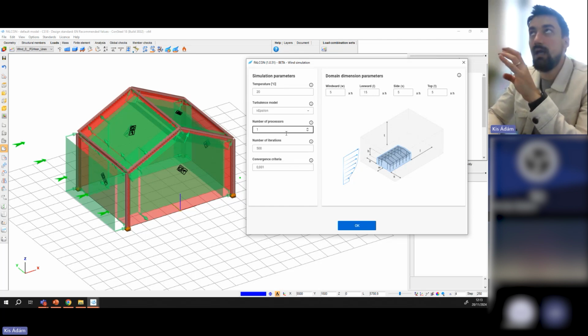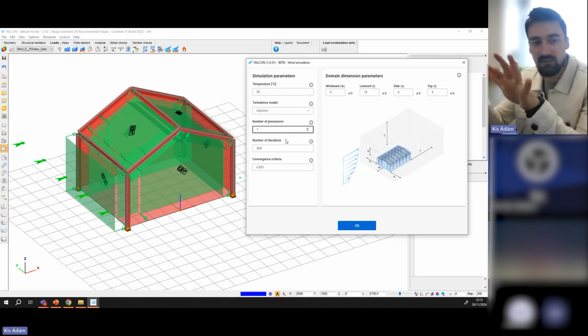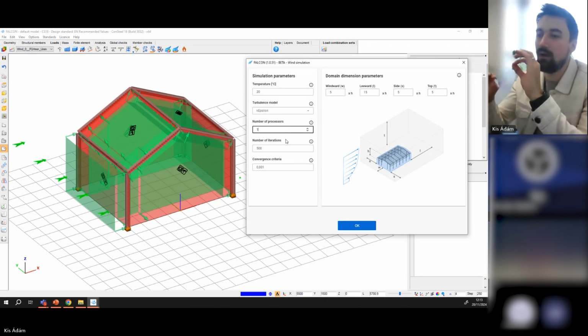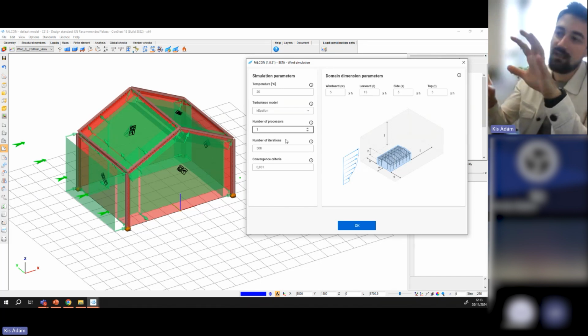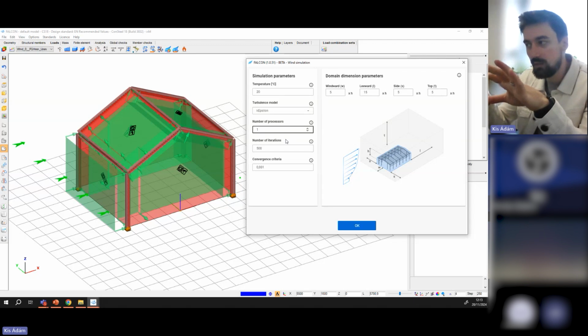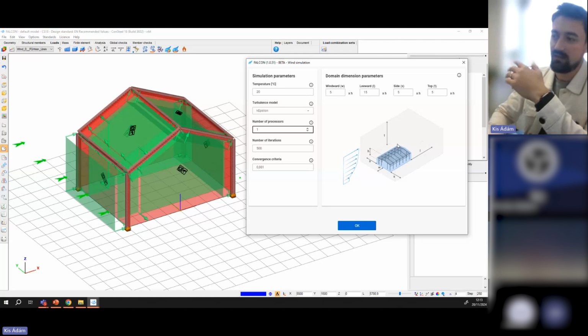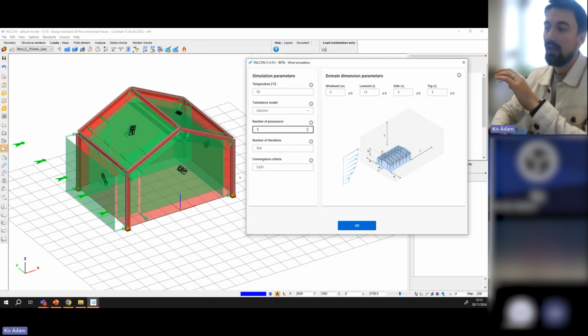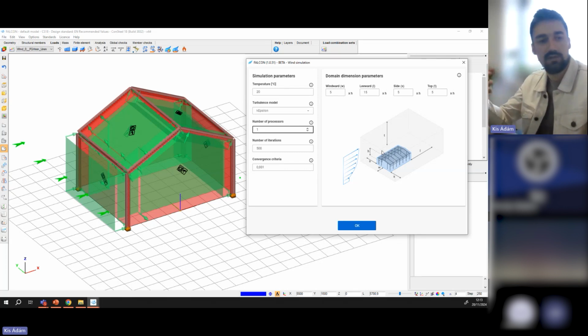When we execute simulations in parallel, both for meshing and for simulations, we have to decompose the simulation domain. If we have 4 processors, the software will cut it into 4 finite domains, and every processor will have its own domain where the calculation will be performed.